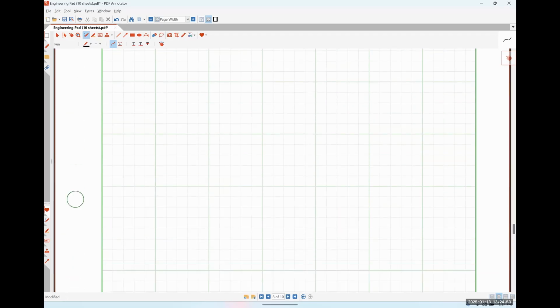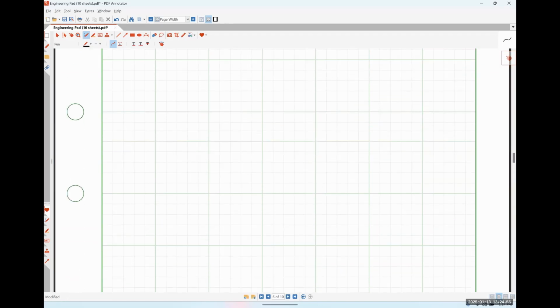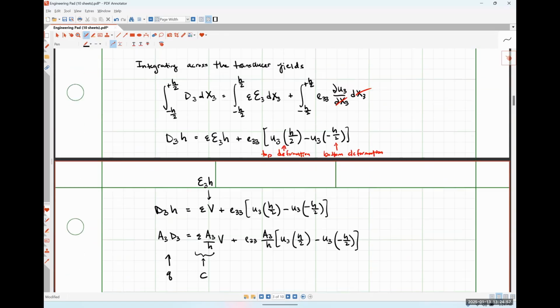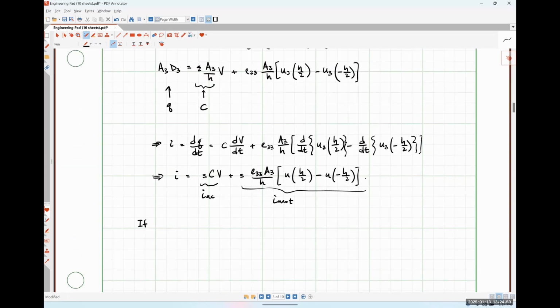Then we've got this motional current thing. And this is how the piezoelectric effect specifically is going to contribute some overall current to our system. So we have some that's coming about from the fact that we are exciting this thing periodically.